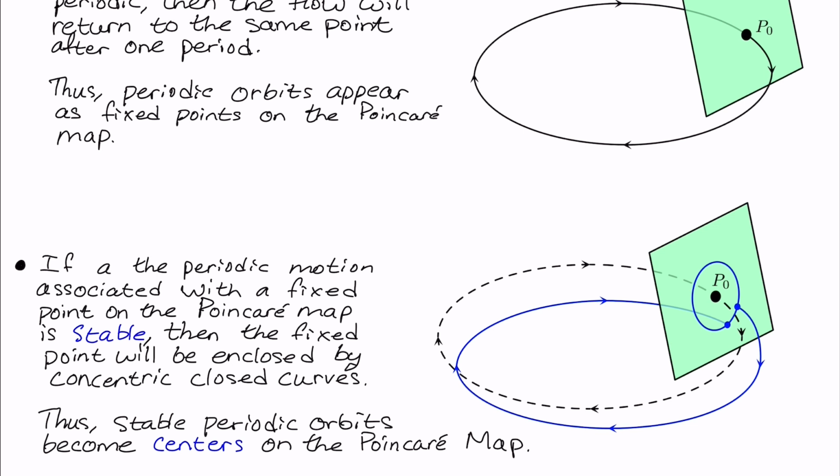And if you recall, in this sense, a periodic orbit is a periodic solution, which corresponds typically in terms of nonlinear vibrating structures to what we would consider a nonlinear normal mode, for example. As you recall from chapter 5, we defined nonlinear normal modes to be periodic solutions, not necessarily synchronous, but periodic solutions to the response, consisting of a single frequency typically as well.